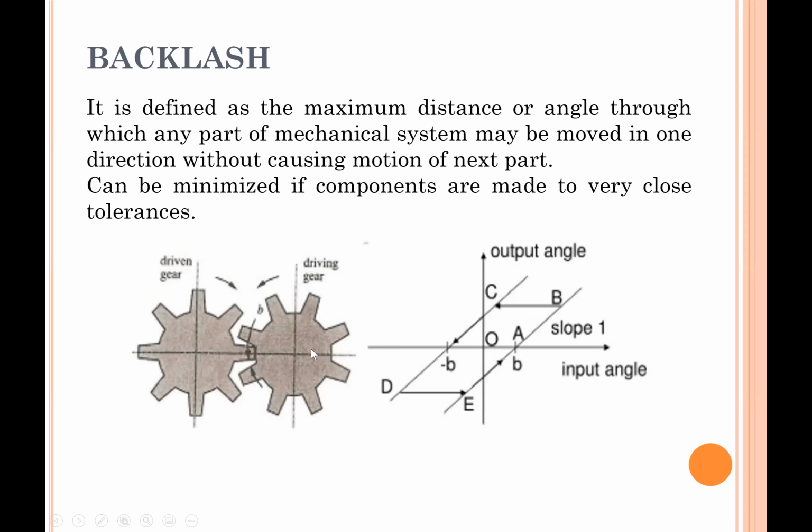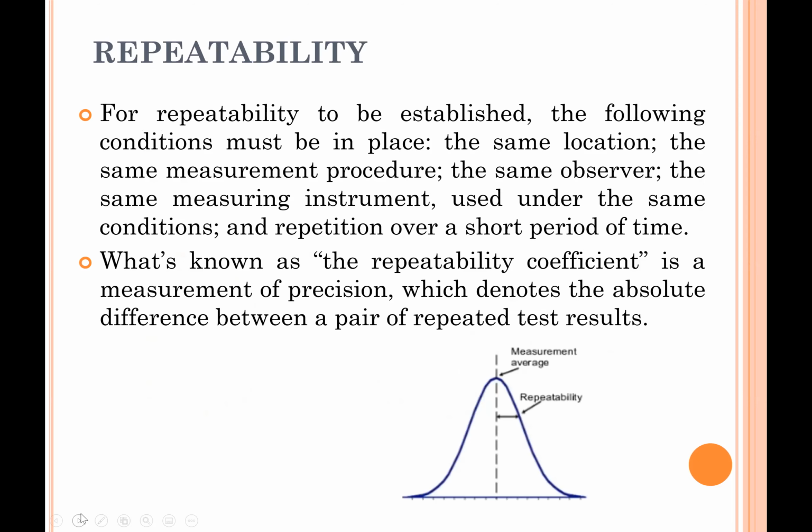Again, this is an unwanted phenomenon. This should not be there, and this can be reduced by designing your mechanical components as properly as possible by having no distances in between. So this is called backlash.